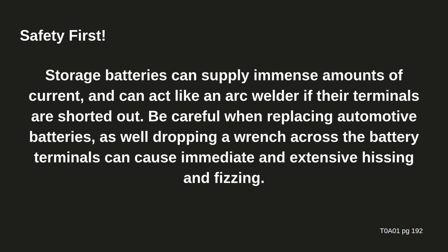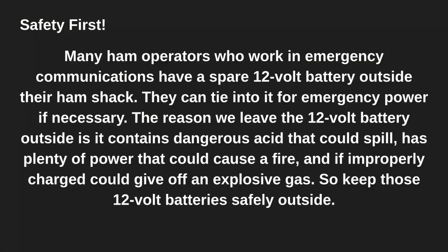Now, storing batteries. Storage batteries can supply immense amounts of current and act like an arc welder if their terminals are shorted out. Be careful when replacing automotive batteries, because we do tend to use automotive batteries, because they've produced enough power for us to do our radios. As well, dropping a wrench across the battery terminals can cause immediate and extensive hissing and fizzing. Now remember, that extensive hissing and fizzing, if that's the one question you get right, that is in the exam.